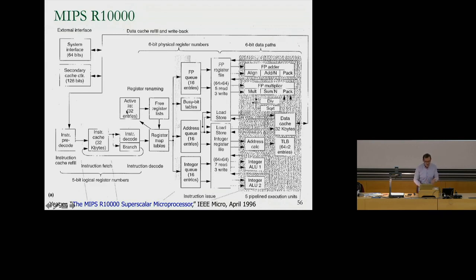As you can see, this is very similar to what we've discussed. You have a register map table front end, you have the schedulers over here, the register file over here, and then the functional units over here. They don't show the other stuff, but that's fine. There's another interesting thing shown here: these free register lists. This shows that you need to allocate free registers, because there's a physical register file. You need to decide when a physical register becomes free and when it's not available. I'll let you think about that. I think one of your colleagues thought about that already.